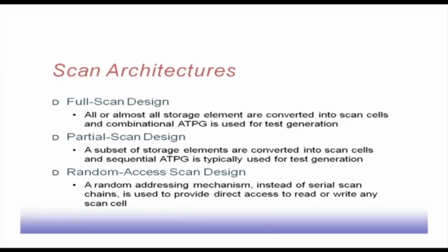flip flops. So, in a full scan design, almost all storage elements are converted into scan cells, and then combinational ATPG is used for test generation. So, here all the flip flops that are there in the design are converted to scan flip flops.